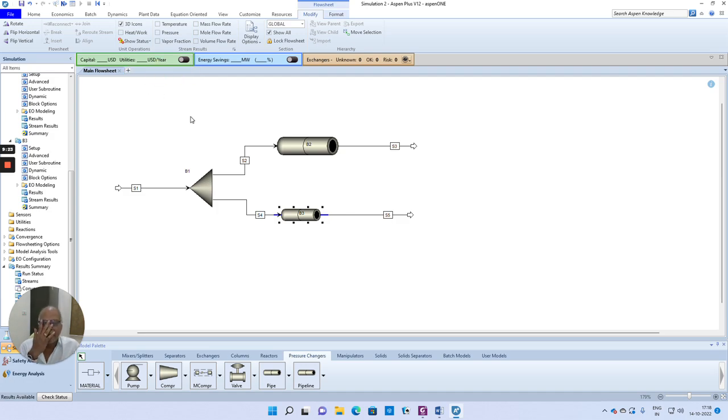So you can think of analyzing this problem. So the optimum distribution of flow should be in such a way that the exit pressures from both these pipelines must be similar. In other words, the pressure drop across each of the pipelines must be similar. Because the input pressure is similar, when the pressure drop is made similar in these two pipelines, the output pressure would be equal, right? So how are we going to handle this kind of a problem?